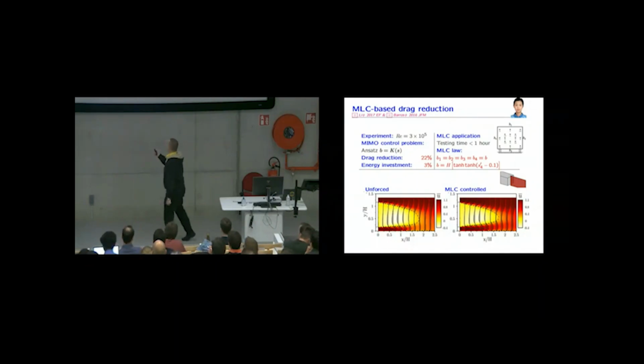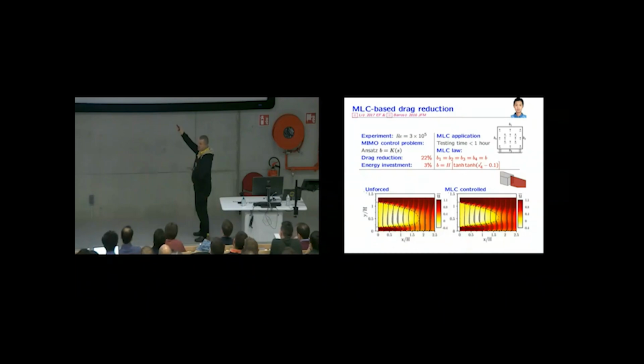So why this? Well, it only listens to this sensor signal because the best forcing is high frequency forcing. And this sensor is the only one where you can essentially sense the induced vortices actuated on the frame. So the other ones have a too large signal to noise ratio. So with this, we get these reductions. Note what MLC did. It has done 3 things: actuator selection, sensor selection, and using the controller, all in one brush. And if you use other techniques, you need to have a linearized dynamics so that you can apply them.